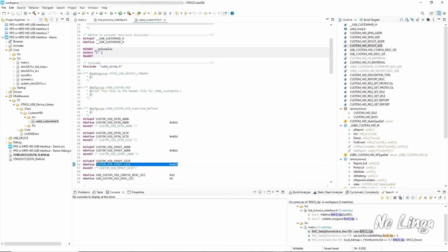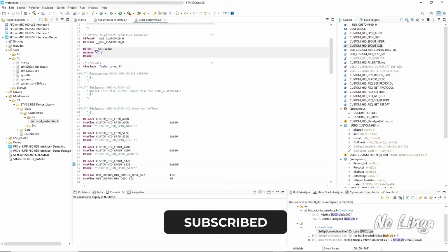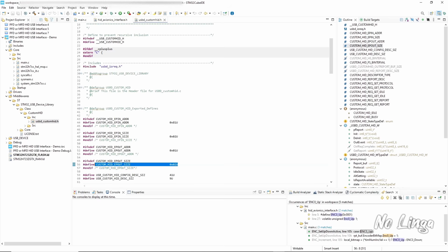So just so you know, in refers to in the computer. We're sending data into the computer over with the HID descriptor, and out is what's coming back from the computer to the board. And this is the size that we're going to change coming back. So just so you know what in and out represents.